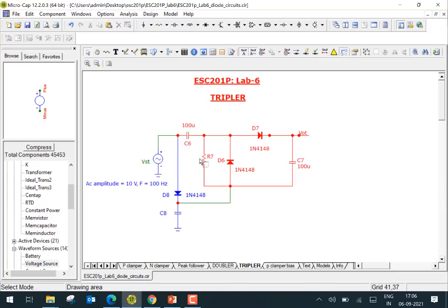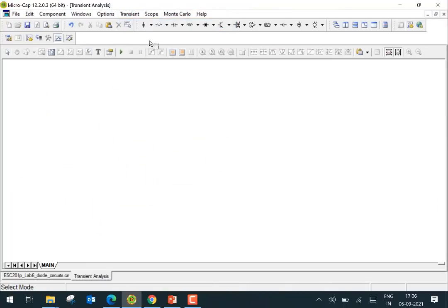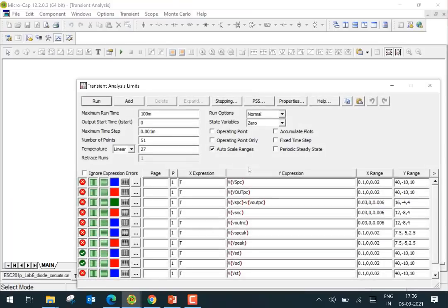So this is the doubler part here. And how are we generating the value here? Note that during the positive cycle, except for the diode drop, this capacitor will charge up to around 10 volt or so, right? This provides the reference of 10 volt, and then the rest of the circuit works according to the way we just saw. So we can simulate and see whether it triples or not.